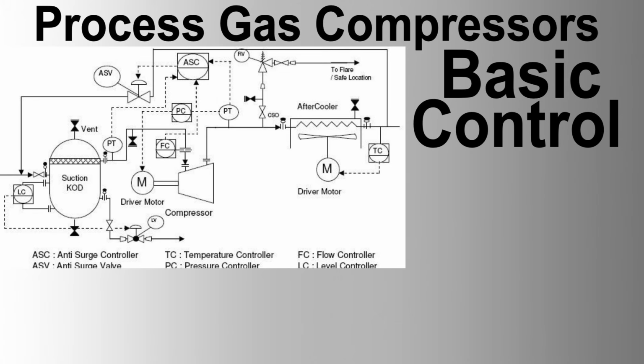Control strategies and tuning. Tuning. Proper tuning of PID controllers is critical to ensure responsive and stable control loops. Tuning involves setting the proportional, integral, and derivative gains to achieve desired performance without oscillation or excessive delay. Feed-forward control. In some cases, feed-forward control is used in conjunction with feedback control. This involves predicting process disturbances, e.g., changes in gas flow, and making preemptive adjustments to maintain stability.